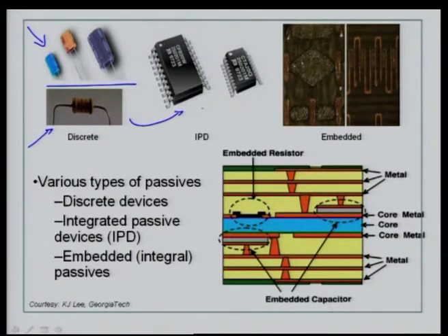and there will be integration done of the capacitors and resistors in this package, plastic package typically. Then came the migration into embedded devices. As you can see in this picture here, this is a printed wiring board on which there are footprints generated for resistors, which have been fabricated in situ of that particular layer fabrication, and then these are connected to the tracks of the printed wiring board to the required interconnect scheme according to your schematic.